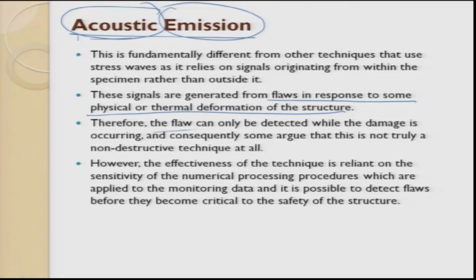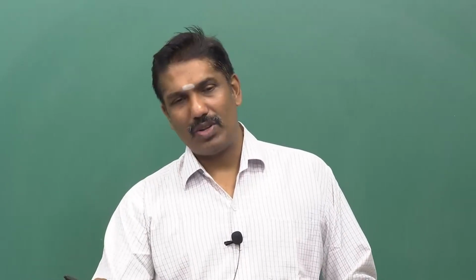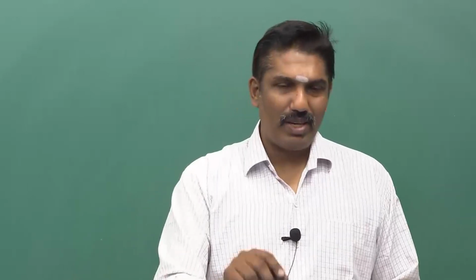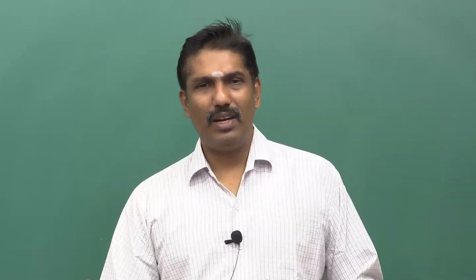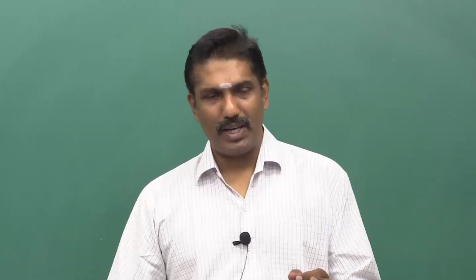Therefore, the flaw can only be detected while the damage is occurring, and consequently some argue that it is not truly non-destructive testing at all. What happens is they say I want some event to happen, and if the event is happening, then it is already becoming destructive. But leaving all those arguments aside, if I can record the signal, the stress waves coming out of the event happening, then I call this acoustic emission.